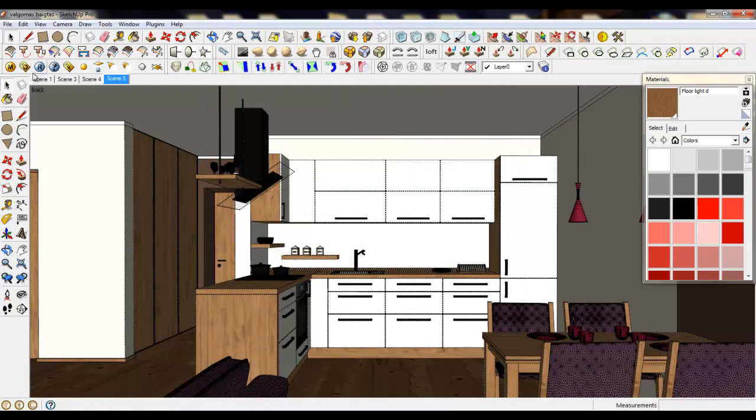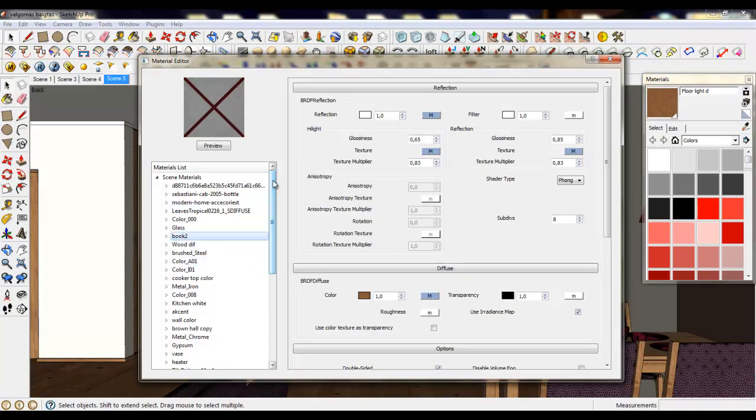Well, we should add some more quality for the textures. For example, the textures which have a reflection, I recommend using more subdivs. So let's type in, for example, 22. The bottle doesn't have any subdivs because it's totally reflective. Highlight and reflection glossiness are 1 and 1, so you can't change the subdivs.